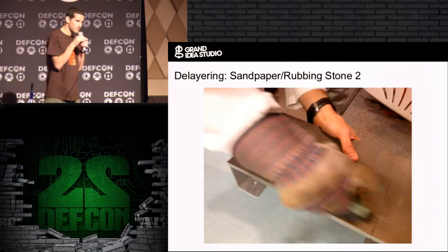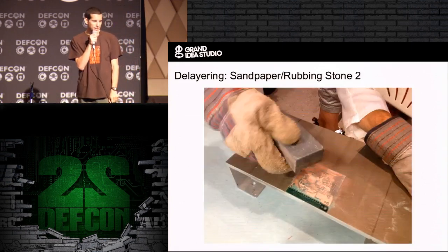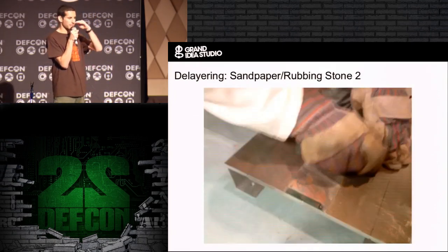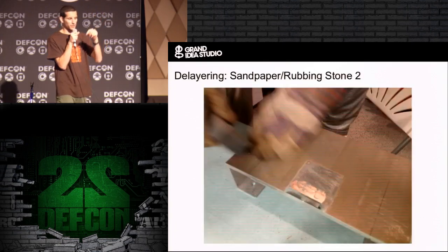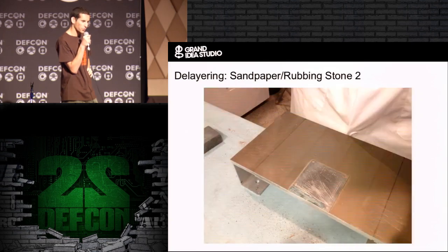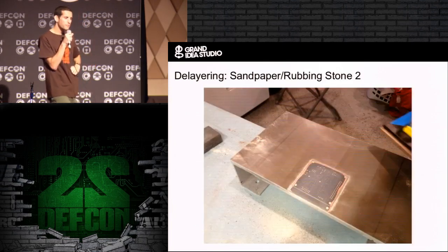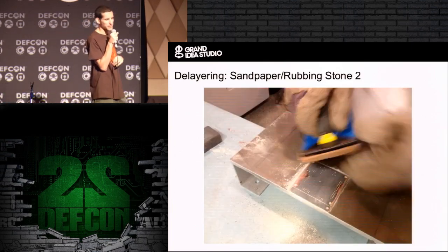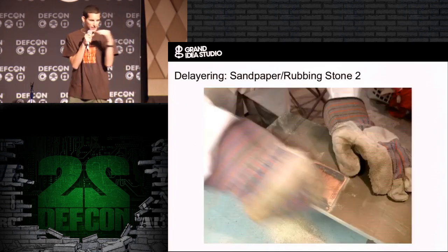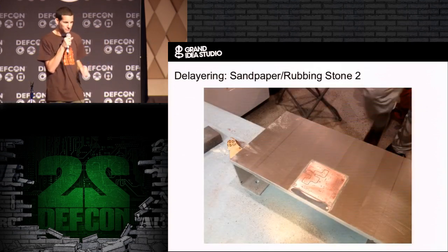Time lapse, of course. So I'm taking the stone, trying to get the top copper layer off, and then we'll have the substrate, and then I got to work on the next layer. So first the sanding stone, try to use that, sort of works. Then I have the sheet sander tool, and little by little it's coming off. But just like with the solder mask removal, you kind of have to be careful about the edges of the board, because if you're not sanding straight back and forth, you're going to have this wear along the edges, and I'll show you the result.